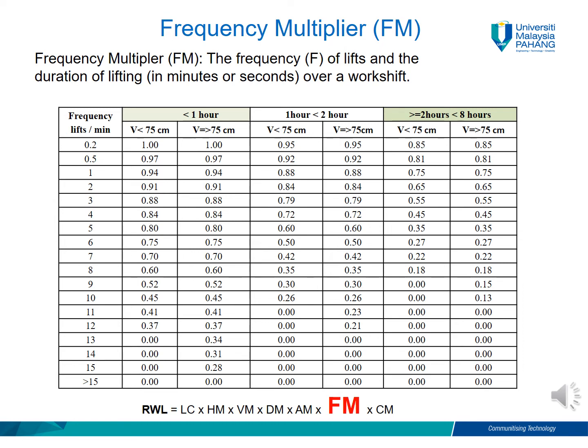Then you need to assess whether the lifting activity is conducted for less than 1 hour, more than 1 hour but less than 2 hours, or at least 2 hours but less than 8 hours. So there are three durations of exposure to be considered.